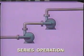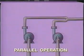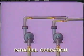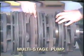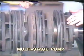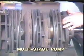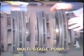When pumps are operated in series, the discharge of the first pump provides the suction for the second. This arrangement is used to increase the pressure over that of a single pump. They may also be set up in parallel, where both pumps have a common discharge. This arrangement is used when an increase in volume is required. A multi-stage pump may be used when higher discharge pressures are required. This pump is like several single-stage pumps operated in series, but the impellers are mounted on a common shaft and enclosed in one casing.